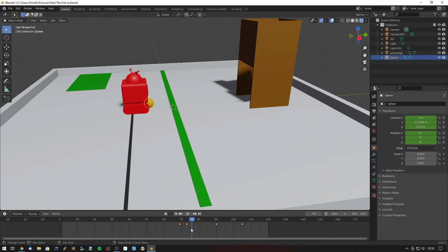So you can see, because I've now changed the end position, the interpolation has changed. So I need to add in a couple more keyframes. So I'm going to move this one to make sure that it's in front of it at that position. Keyframe, location, rotation, hit the I key. Let's just go through. Yeah, that looks bonk. Yeah, it seems to be stopping here.